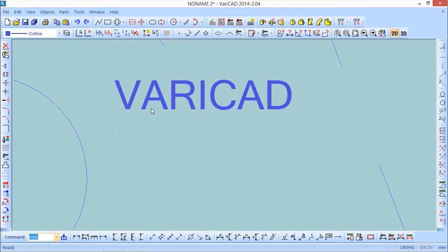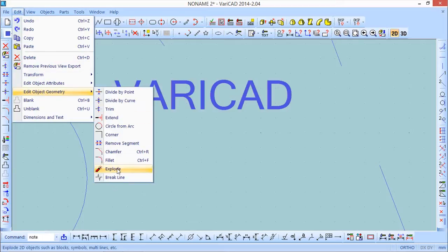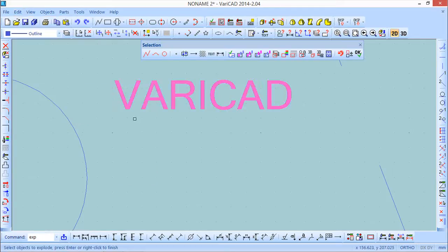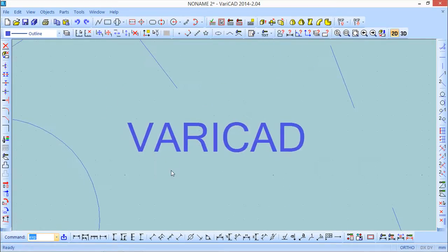It is a little more complex entity than single lines, and you see that this has thickness due to the font that was chosen. But let us see something interesting, which is edit, explode, and if I do the explode, now it will create more.